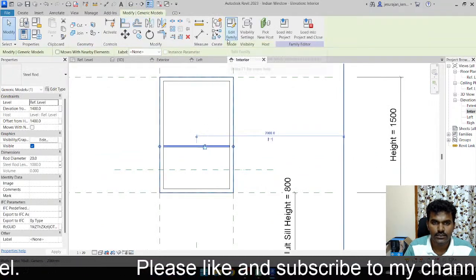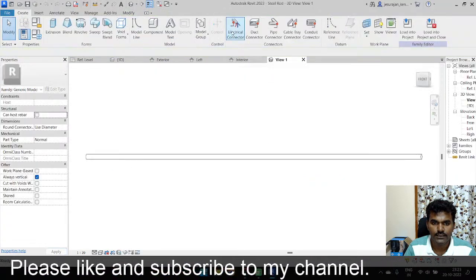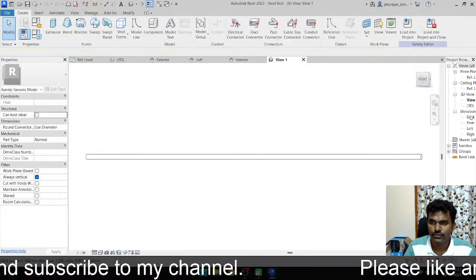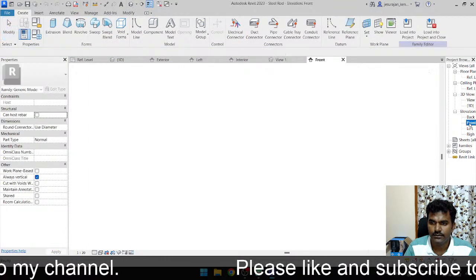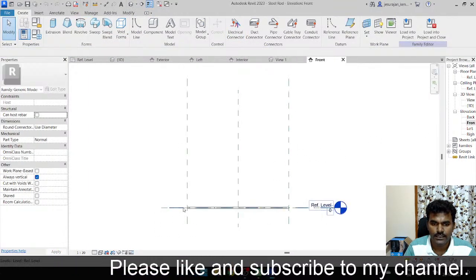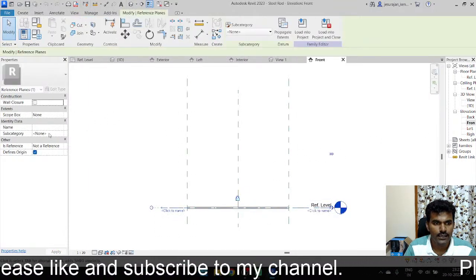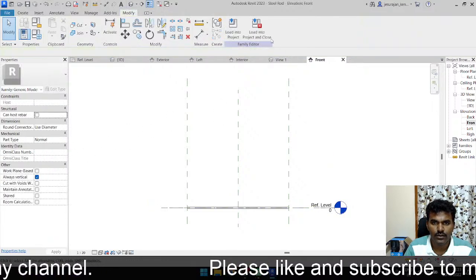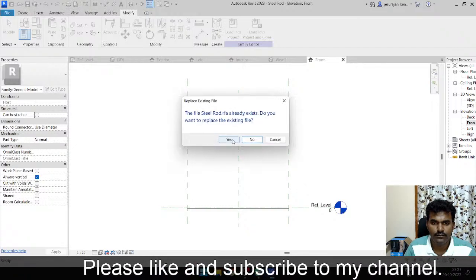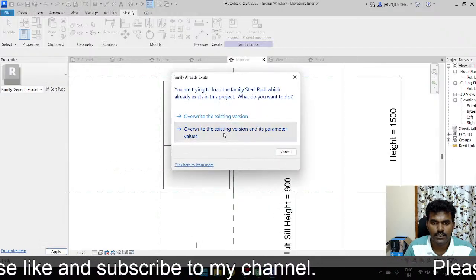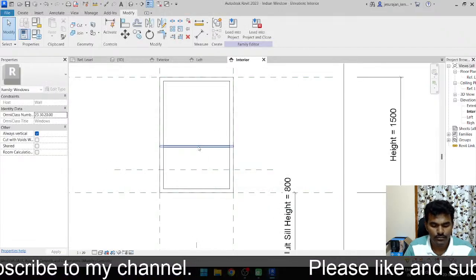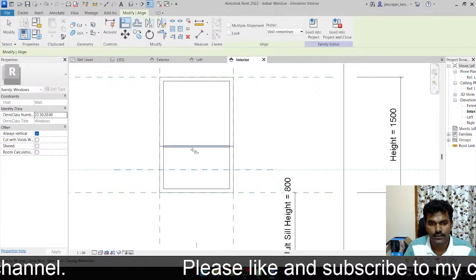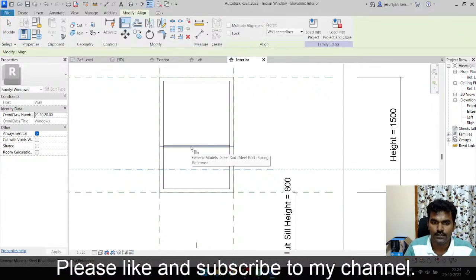Select, go to edit family, go to front elevation, and select the reference plane and make this as strong reference. Load into project and close, save, yes, overwrite. Now try to align again. See here, you can align.